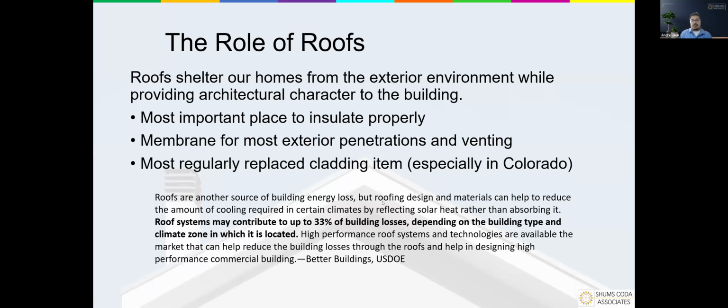I see a comment here from Brian. It's been my experience that in most environments attic ventilation is crucial, but in Colorado, it's just a way of allowing snow and moisture into the roof assembly. It actually defeats the purpose of ventilation. Brian, you were spot on.